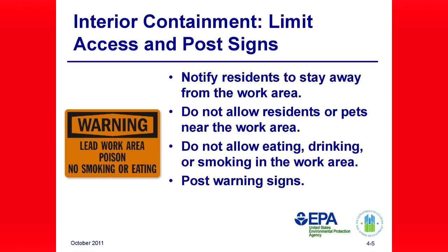Post warning signs. Before beginning the renovation, post a sign for the residents in their native language to warn them or other persons not involved in a renovation activity to remain outside of the work area. Signs must remain in place and be readable through the completion of the renovation and the post-renovation cleaning verification. A warning sign must be posted at each entry to a work area or at each main and secondary entryway to a building from which occupants have been relocated.